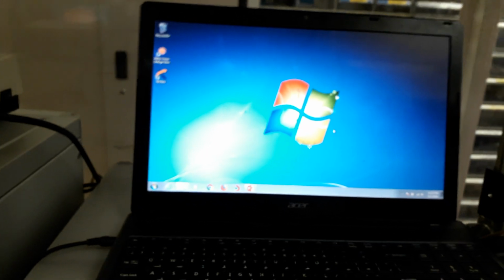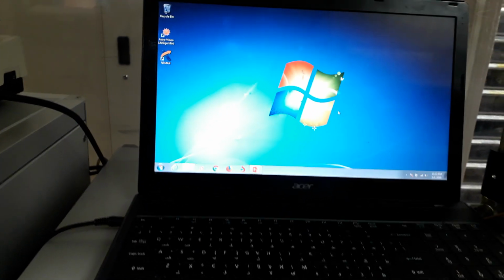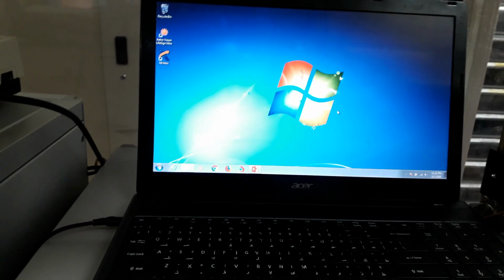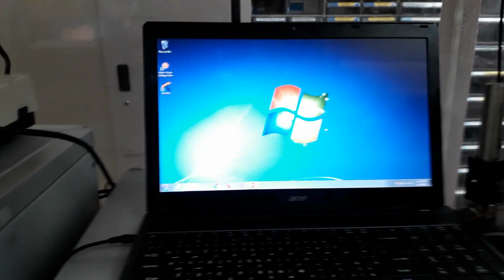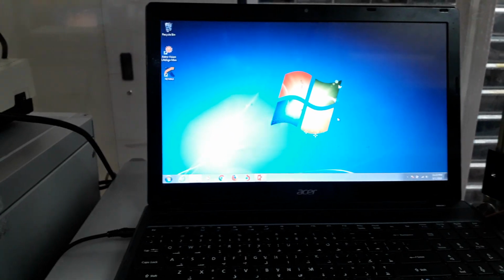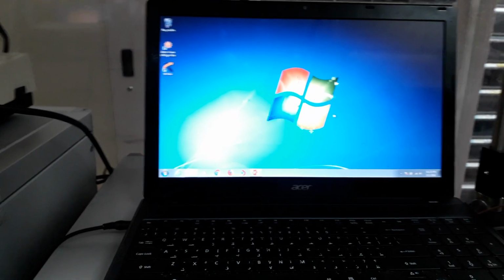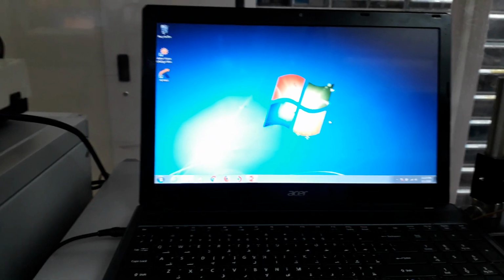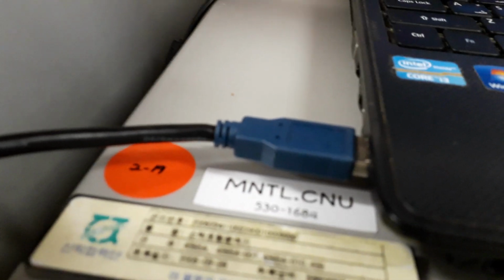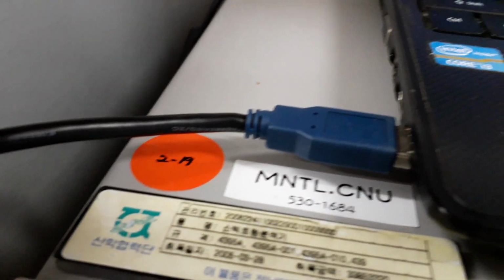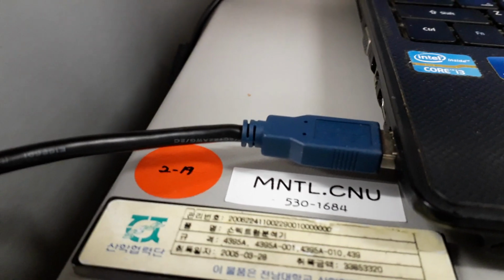Here I am going to connect my system with my network analyzer using a GPIB USB cable. If you use products from one particular company, that will be better for synchronization and compatibility issues. So here I use all NI products. You can see I connect my National Instruments USB GPIB cable. This is connected at the back of the network analyzer in the GPIB port.